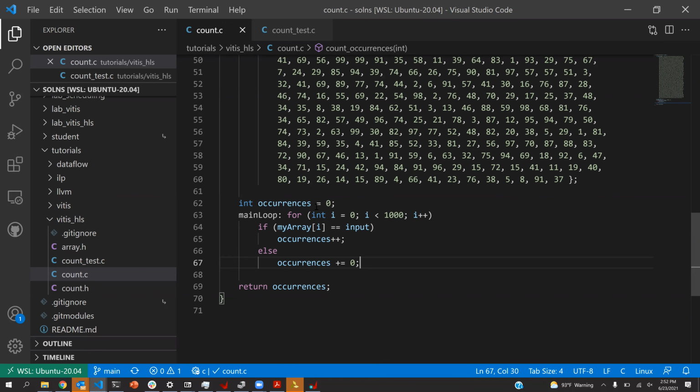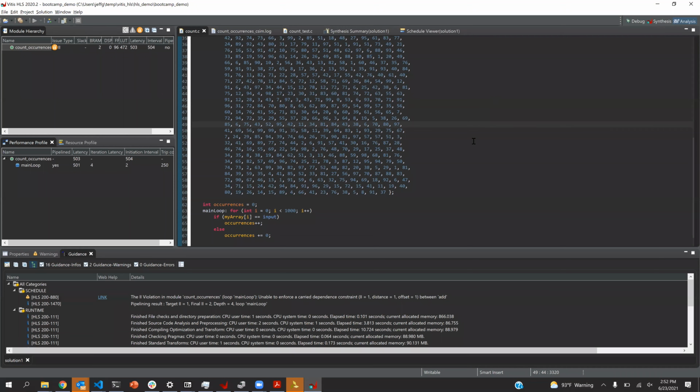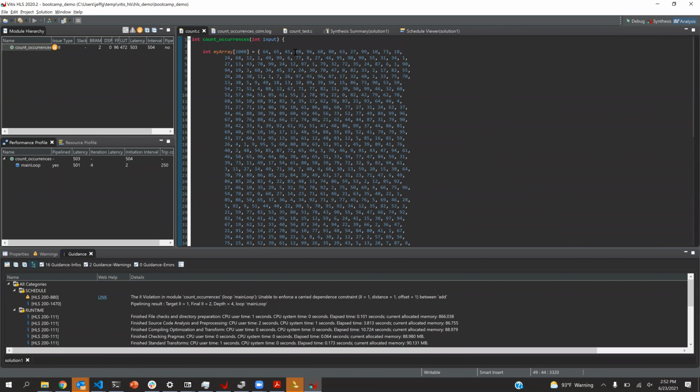Usually you don't have hard-coded values, but if it really is just a ROM like this, a lookup table, and you need to check how often something's in it, you could split it into different memories. I could split it into different memories manually, but again, that's horrible. So I'm going to tell it to do that for me.